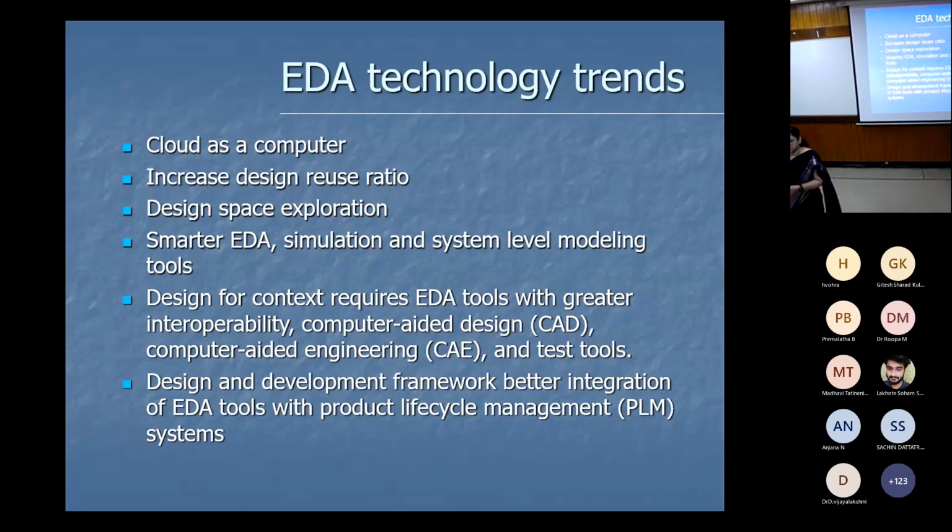So initially, when we had a soft design flow, we just concentrated on that design. We never bothered about what happened to the previous designs which we had done, right? We just went through the database which was relevant for the current design. Here, what I'm saying, when you're talking about the solution level, you need to look at the various. For example, you are talking about the placement. Placement is okay. You figure out by doing trial and error and do the placement. But that is not enough, is what I'm saying. For a previous AI chip, probably you would have used 100 iterations and you figured out the best optimal placement. So you can take that knowledge here and adopt it.